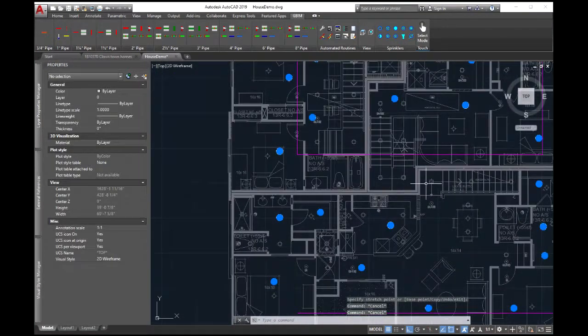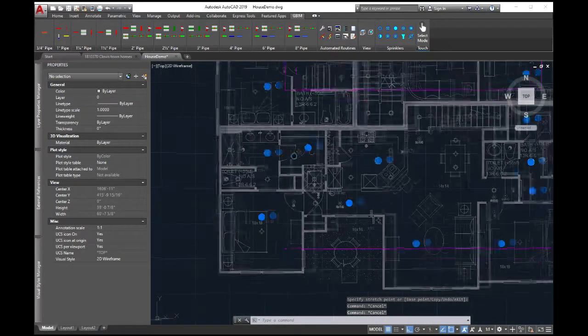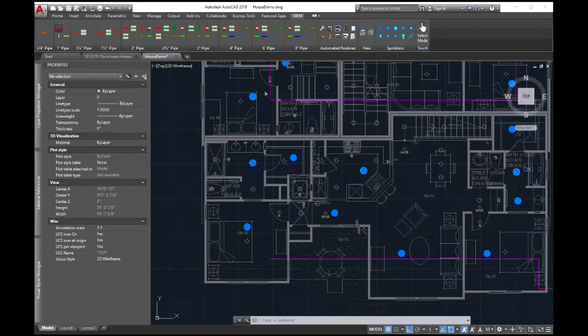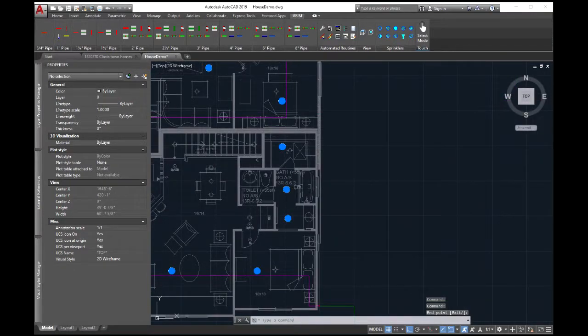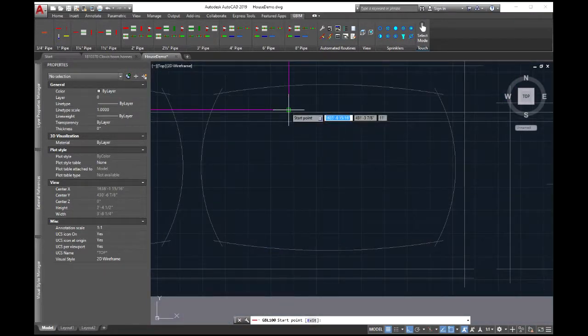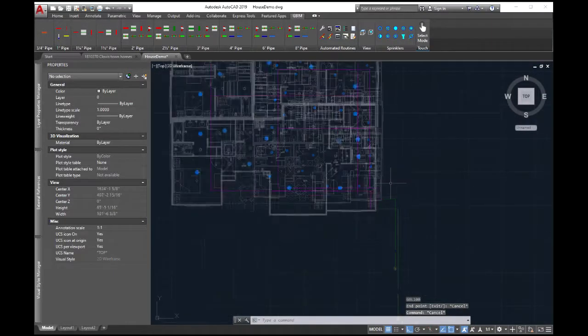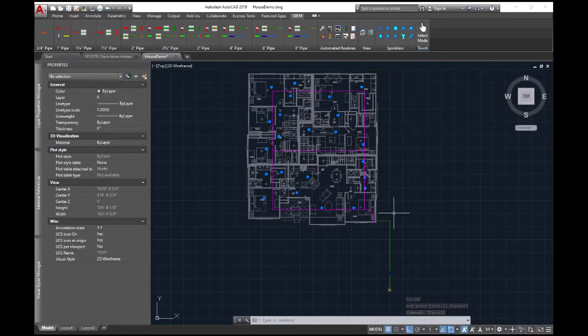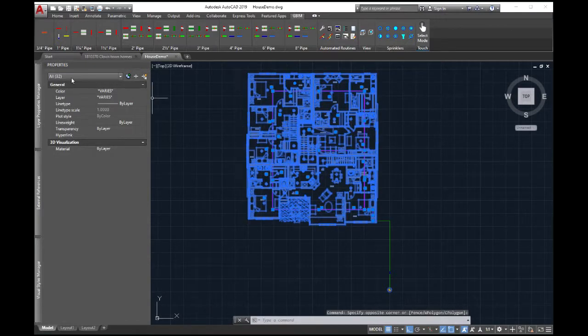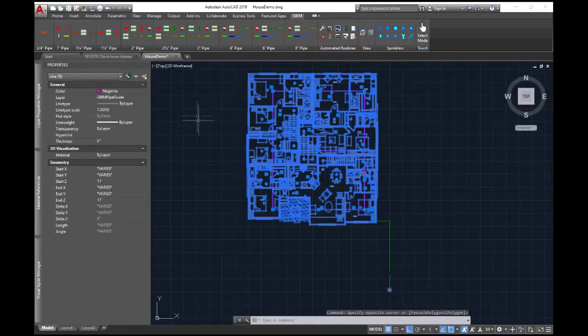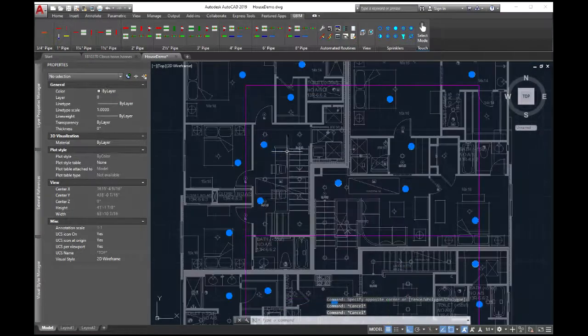The reason we have to do this is that water needs to flow through this pipe. And so now I'll get some more of this 1 inch pipe and I'll reconnect these at the junction points, and make sure we snap perfectly to our pipes. We don't want to snap to anything else. And okay, so now just to make sure, I'm going to grab everything, but I'm going to look at the lines that I just drew and make sure that they're all at 11 feet. So they all start and end at 11 feet, so they are elevated higher than the sprinklers.